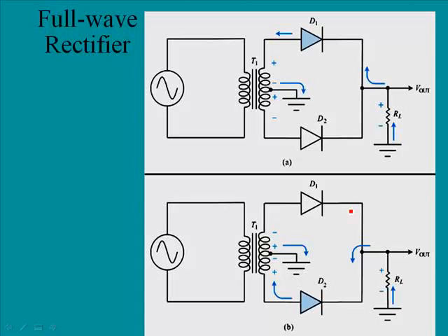And when we say full wave, why don't I first describe what that means? Well, here we had an input wave coming in, and this is the positive, this is the negative. Now with a full wave rectifier, what we're going to get as an output is something that's going to look kind of like this, so that we're utilizing both the positive and the negative side of the input waveform, unlike the half wave that was only able to use half of it.